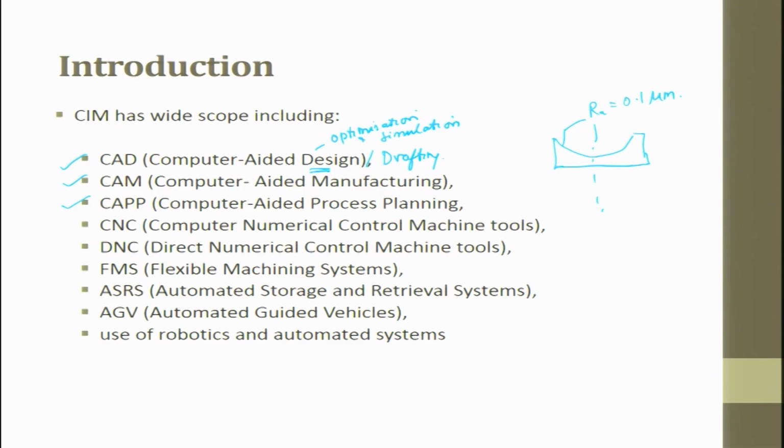So now the challenge is, by looking at the drawing, the computer itself goes back and it iterates and finds out which process to be used, or it gives you a guidance which process to be used, so that the process planner can quickly take it. Maybe he has to iterate it a little bit, but at least a starting solution is given to him so that he can start working on it. Here the component is offset, so when you use a lathe machine, you have to be careful. So these details will be given by the process plan.